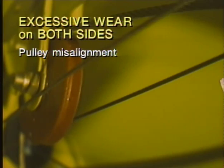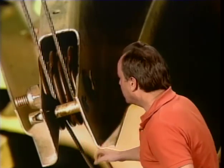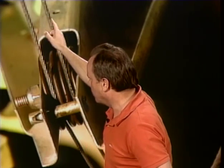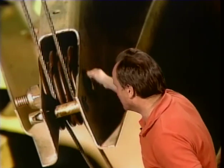pulley misalignment. Now, let's talk about inspecting the controls of an aircraft. A satisfactory method of inspecting control cables for broken wires is to place a piece of cloth around the cable and run it back and forth over the length of the cable. And what happens is, if you get little broken wires, it'll catch on the cloth. Now, another way you could do it, not recommended by the FAA, is just run your hand back and forth and just check for blood in your hand. Now, I think I'll use the cloth instead, if you don't mind.